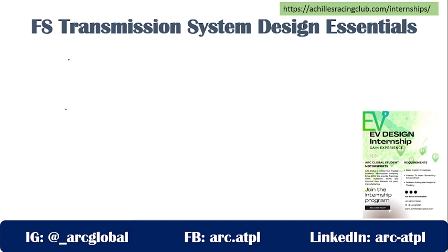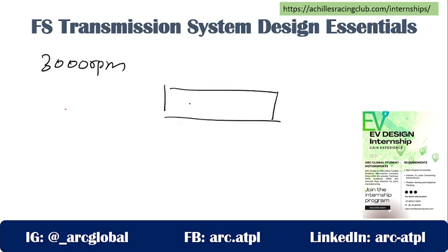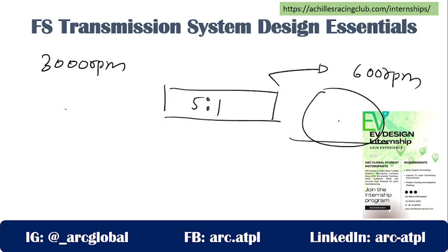So now I have this understanding that if I need a higher velocity, I need to use a tire having a higher size. Now my engine is producing 3000 RPM, and in between I have a 5:1 gear ratio. That means I have 600 RPM available at my tire. At 600 RPM, what velocity will I have if I use X size of tire or Y size of tire? This is how you need to calculate it.